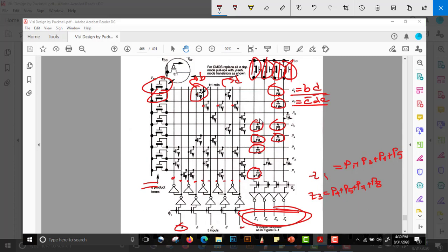One thing to be noted is that using PLA we can perform or make any logic function using AND and OR gates. But one thing to be remembered is that once we fabricate this PLA, it can perform only one logic operation, the one that has been designed using the MOS. That is, each PLA that we design will have 5 inputs, A, B, C, D, E, if designed in this way, and 4 outputs, Z1, Z2, Z3, Z4, and the operations they perform will have to be stated.